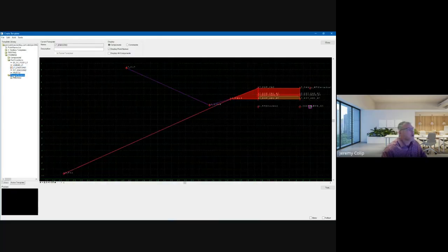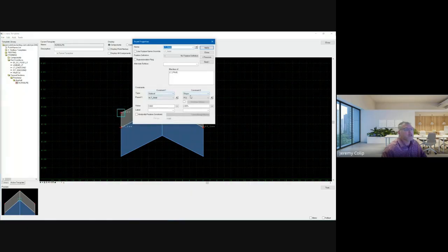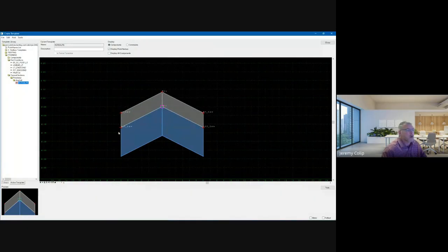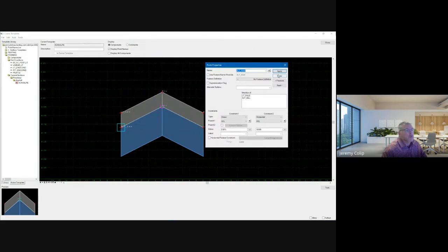All right, so what you all see on the screen is this model right here. I have a left saw cut, a right saw cut. We went over this template a little bit yesterday, but you can see how I named them, why they're named the way they are. They have some different conditions. So this one I'm tying by vertical and slope. The bottom ones I am tying by same thing, slope and horizontal to the control point in the middle here at the bottom.